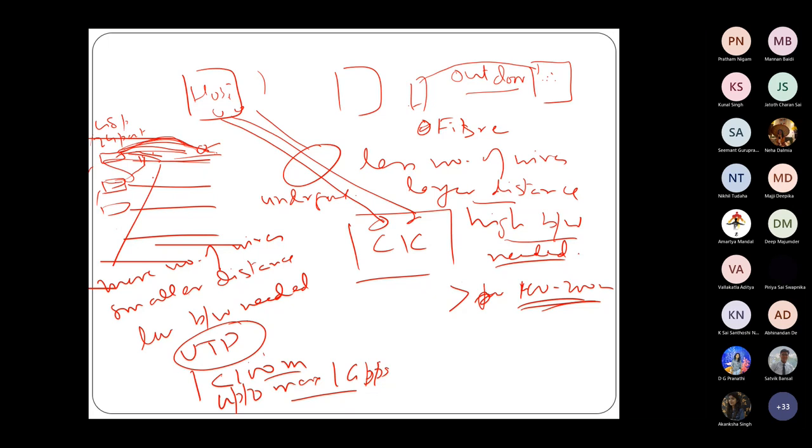You don't want to do this because outdoor, remember, is subject to impulse noise. And worse, you have seen a place like Kharagpur, for example. Your design has to take care of a lot of things. It's a place where it's absolutely dry, storms almost never happen. But here, lots of storms happen. There's a lot of lightning. And the lightning will not just corrupt your data, but that electrical interference will propagate to the two ends and burn the switches.